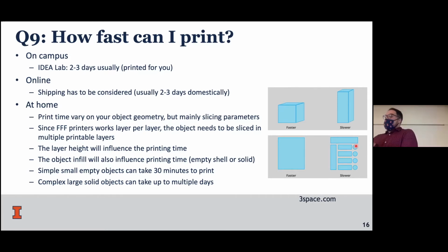It took more time to print for that reason, but just printing the cap wouldn't take too much time, and then I could glue it on. But you really need to position it in a very precise location so that the printer starts there. If you're offset by just a little bit, you're going to have a blob of filament extruding in the void. So that's why it may be worth spending a little more on a printer that has the power-out recovery option. It's been handy a few times.